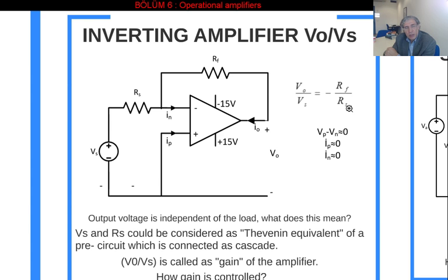As I said already, these two serially connected elements represent the whole circuit which is connected to here, and I cannot play with this circuit, but I can play with this feedback resistor. By playing with that resistor, I am controlling the output voltage or the amplifying degree of my circuit.